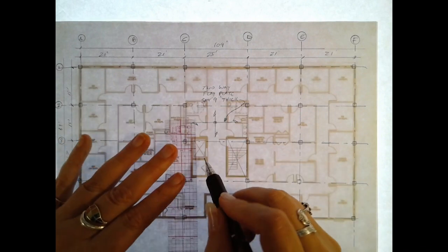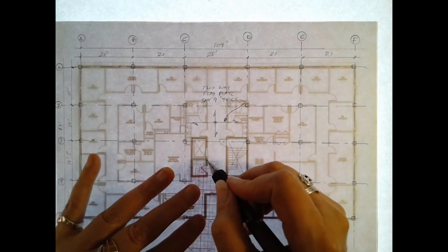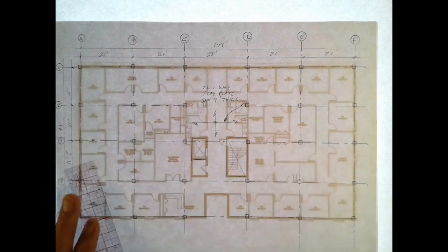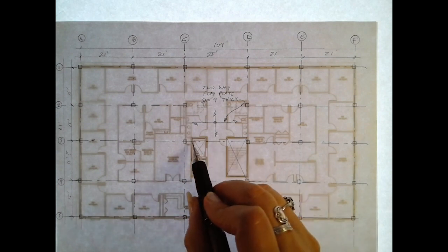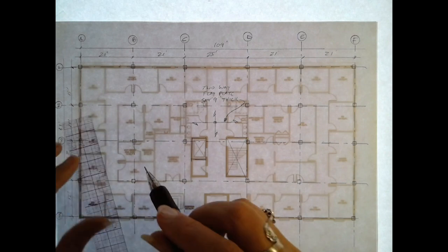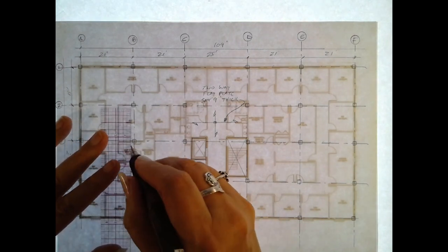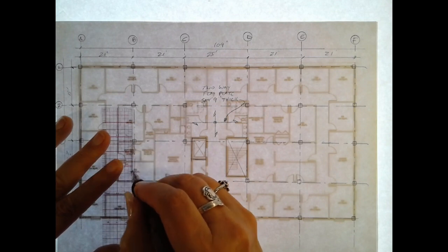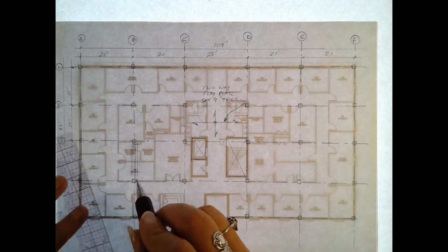There's the elevator right here. And this poses very interesting challenges right off, because the way a slab is reinforced commonly is to have embedded reinforcement that mimics a beam, even though there's not a beam in there. It's the same thickness. So let's let this represent the reinforcement for a slab.